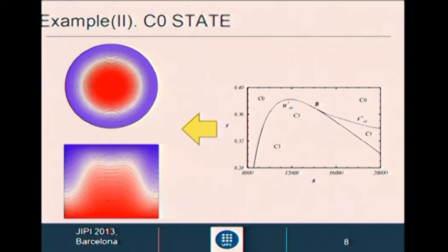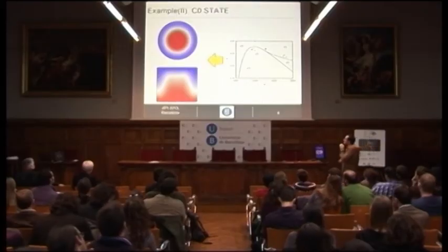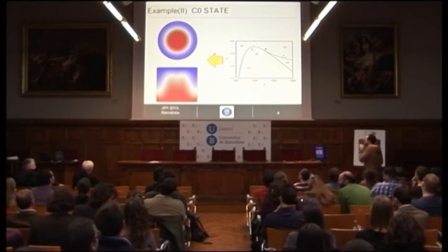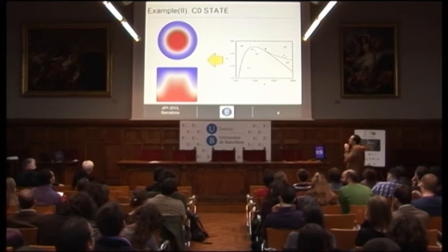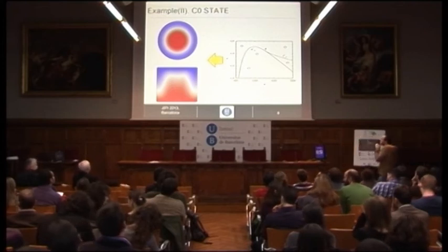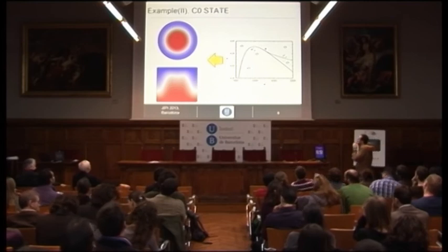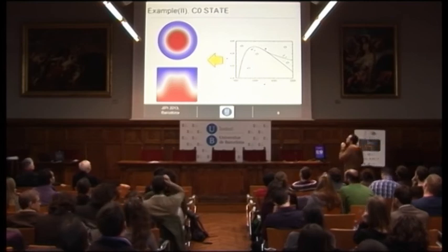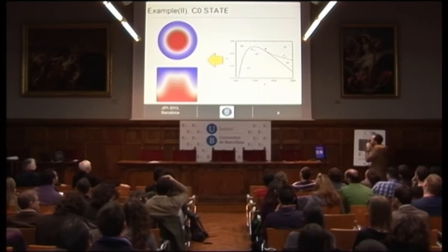The first thing we have to do in this kind of analysis is to calculate the basic or laminar flow. So here I show you the temperature corresponding to the basic flow of this system. It's very easy to describe in the lower picture what is happening here. The warm fluid at the bottom, which is lighter than the cold fluid, goes upward, and at the same time it is centrifuged towards the center of the cylinder, while the cold fluid goes to the outer part of the cylinder. In the upper picture, you see the axisymmetric character of the solution.